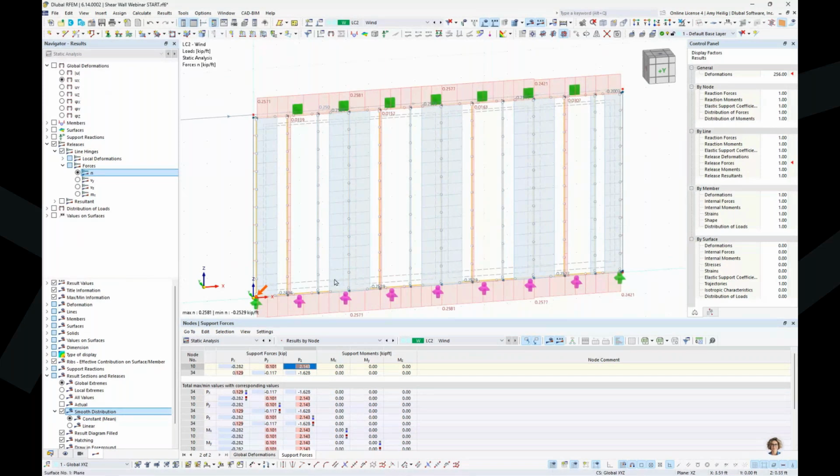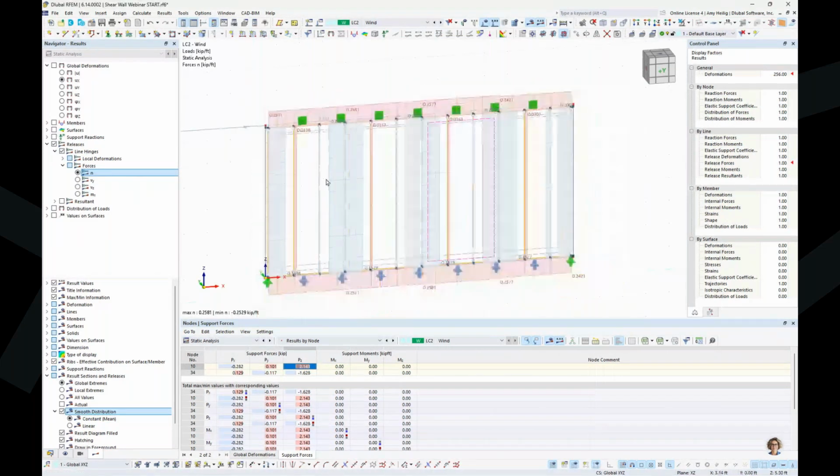And also remember, the sheathing panels themselves are not one continuous sheathing, but they are in those 4-foot increments all modeled here. So all of these come into play with true FEA. So that's why we might see slightly different forces here for our shear force, again, versus something like hand calculations.